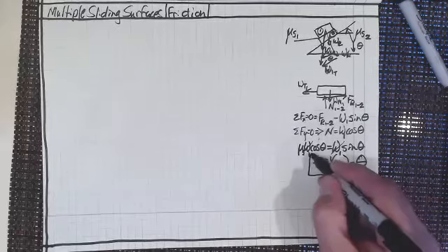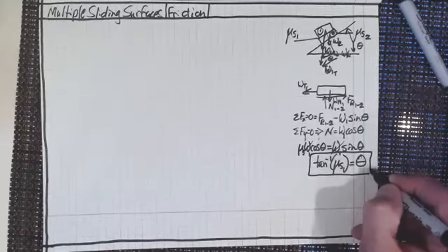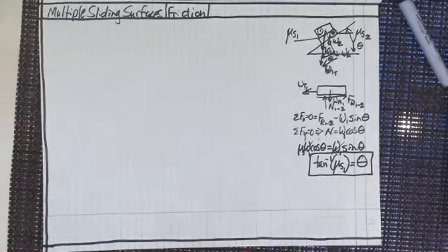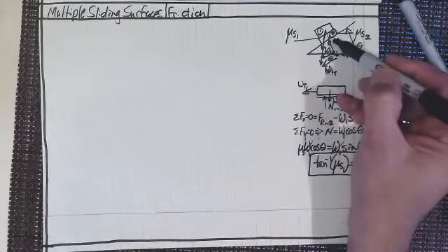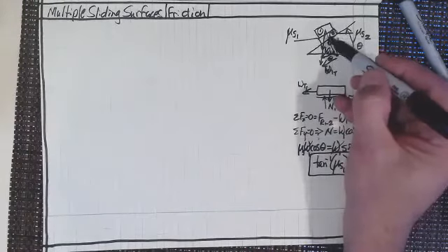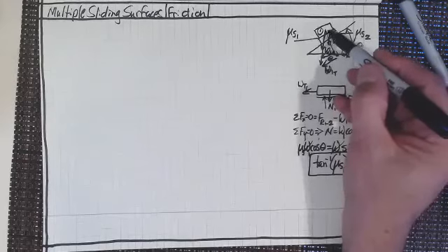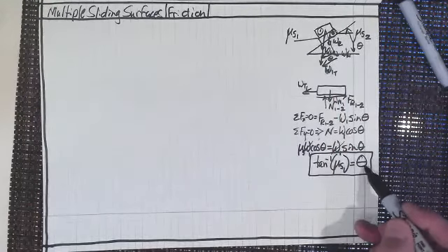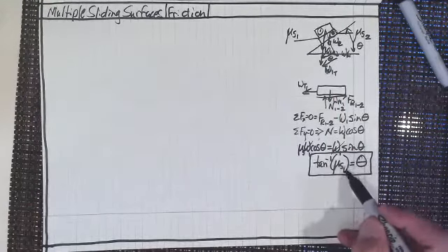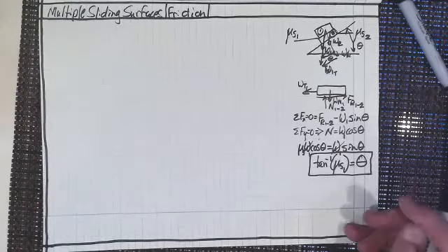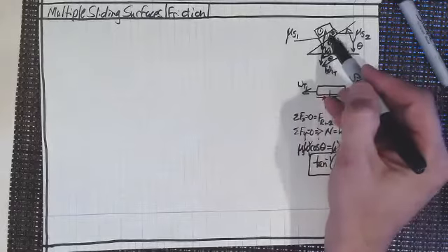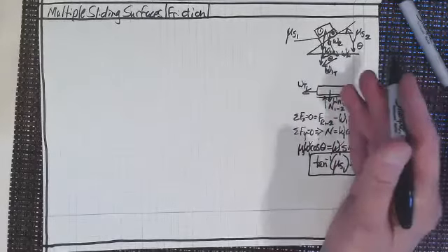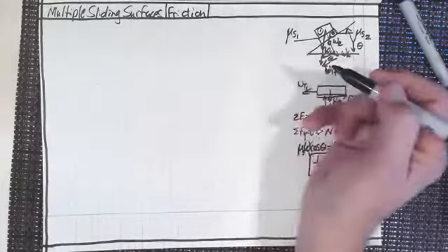So that would tell us what the angle is that this is rotated to, at which point this will slide relative to the block right underneath it. So block 1 is going to slide when the angle equals the inverse tangent of mu sub s1. Now, let's analyze the second block, the free body diagram of the second block now.